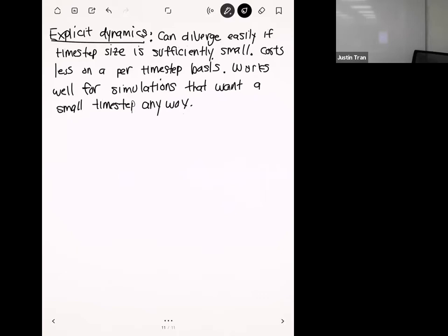Some people will definitely be getting this, but not enough. I'm getting my max deformation. It's interesting to see how many people have not. Usually you won't get it if you have a small element size, but with this one, if you make the element size smaller, you're going to run the element count up by a ton, and you just can't work from there. So we're going to report that.